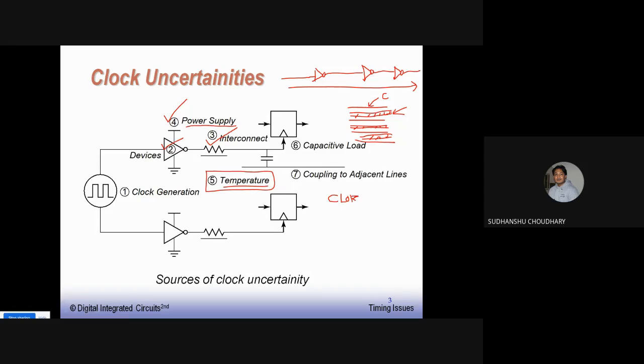I think we haven't talked about this clock gating. So let me tell you that clock gating means that in the portions of the chip where you don't want the clock to be connected, maybe let us say that this portion 2 of my chip is idle, so I don't want to route the clock to portion 2 of the chip, right?